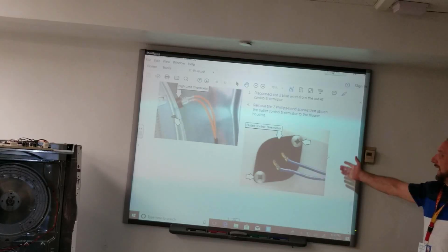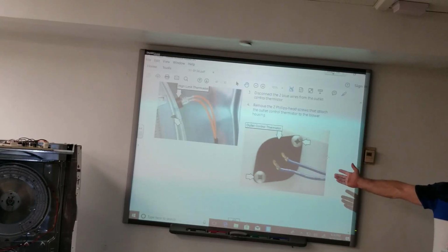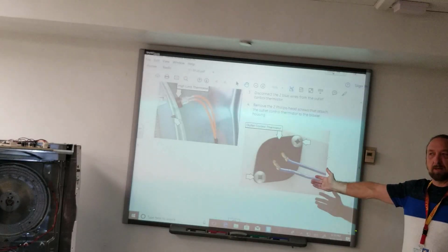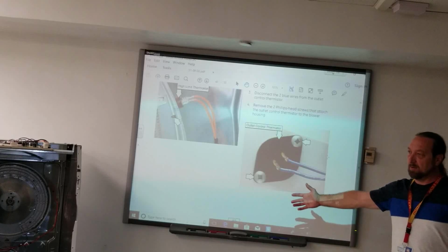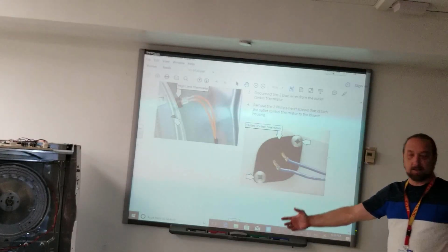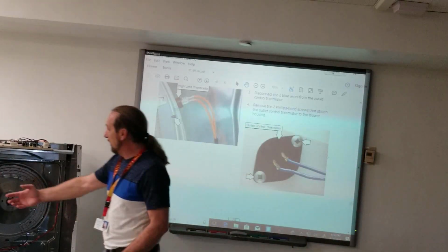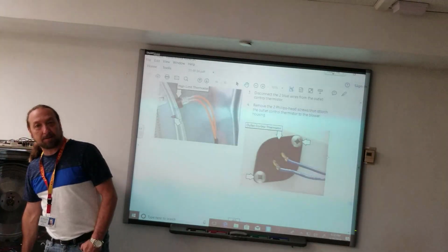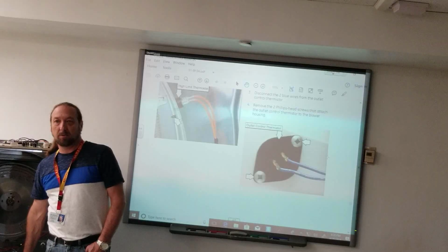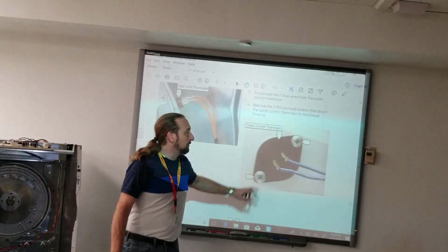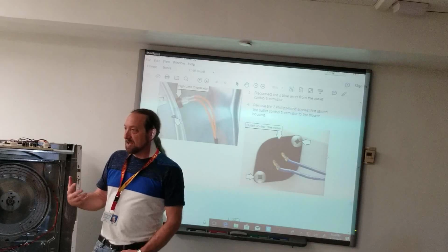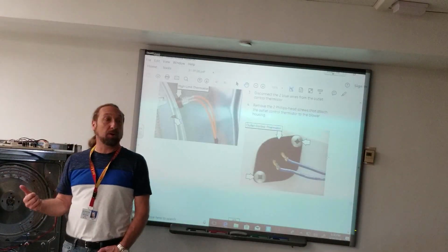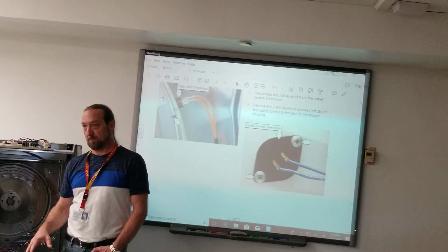This is our outlet control thermistor. Where is that one located? What's the first word? Out. So that's where the air is going out. Before we were doing inlet. Remember at the beginning I said air comes in over the element. It goes out through the fan. So we're talking about down here on this housing. The outlet control thermistor is the main one that's doing the job. That one is telling the control board it's 140 degrees, turn off the heater.